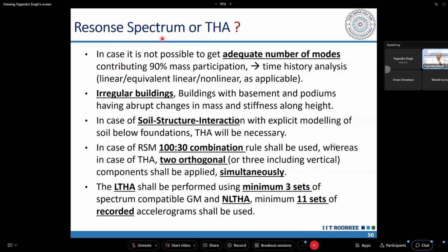That's how I can design the well. So that is quite accurate. Or I can perform a time history analysis. If I perform a direct time history analysis, then all the masses, all the modes are inherently considered. Everything gets excited depending on its period. So if we are considering soil structure interaction, then also we may have to go for time history analysis.